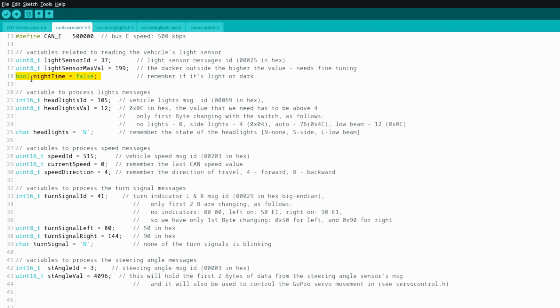And this brings us to a very important point, that CAN bus is an event-driven system, which means that the frames or messages are not put onto the CAN bus all the time, but instead are put there or sent down the bus when some event occurs, which means when this or that sensor's values change.